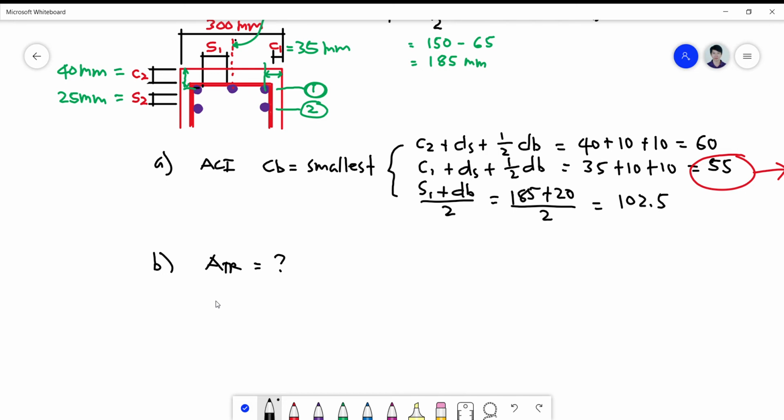So for a corner splitting, your area is simply always twice the area of the stirrups. Okay. For intermediate splitting, or I'm sorry, it's actually equivalent to 1 times the area of the stirrup only.